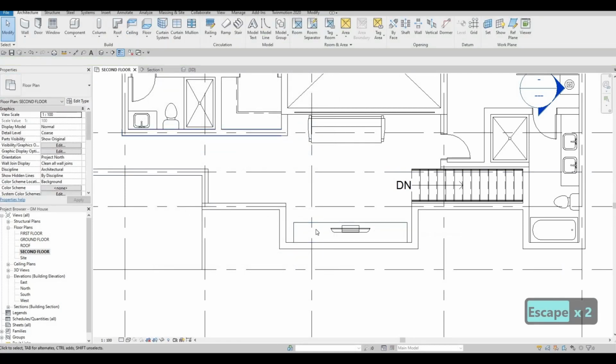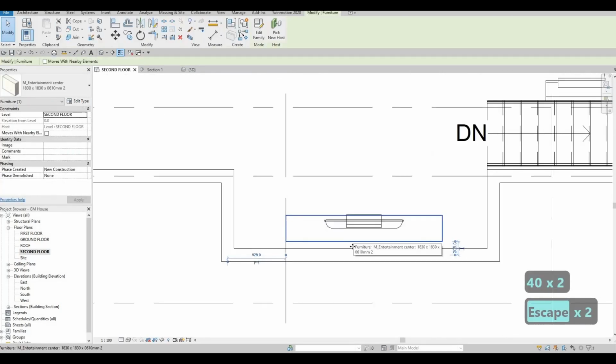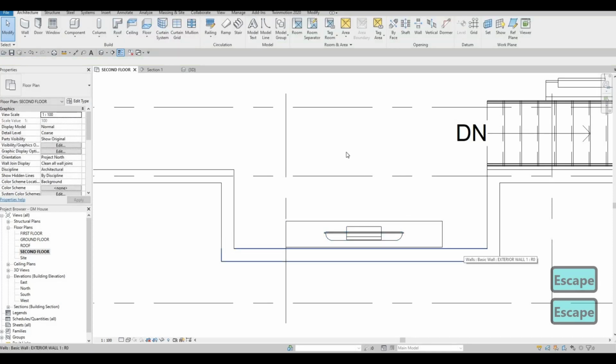So for now, let's select that, edit, duplicate, and then we're just going to put this one around probably 2400, and then the width is something like 2500, this one 100, and then depth is around 400. So I just want to make it smaller so that we could add in something right here. So some windows right here.